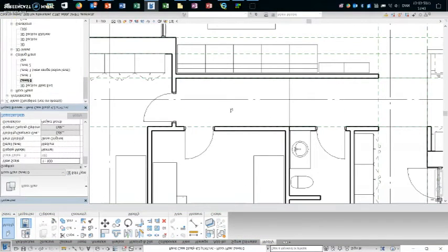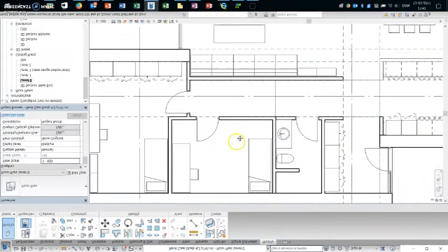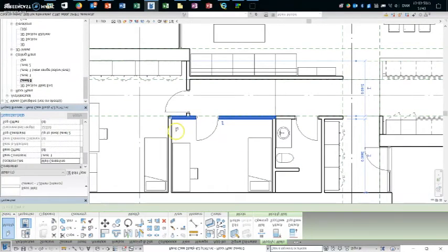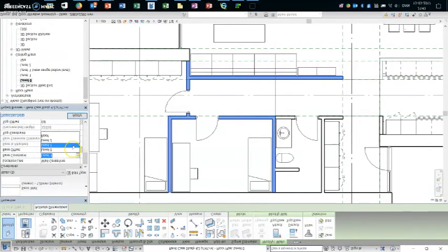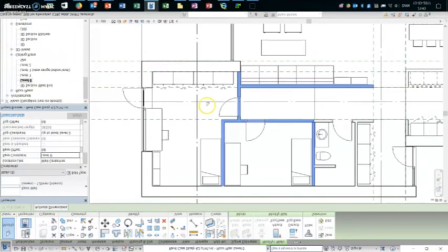Now after we've split the walls, we have to attach them differently, so we choose the inside of the walls, the inner walls right here, these 5, not the toilet, right here, and we attach them to level 0 instead of level 1. The same procedure should be done with all the windows and the doors, of course, and all the internal furniture.